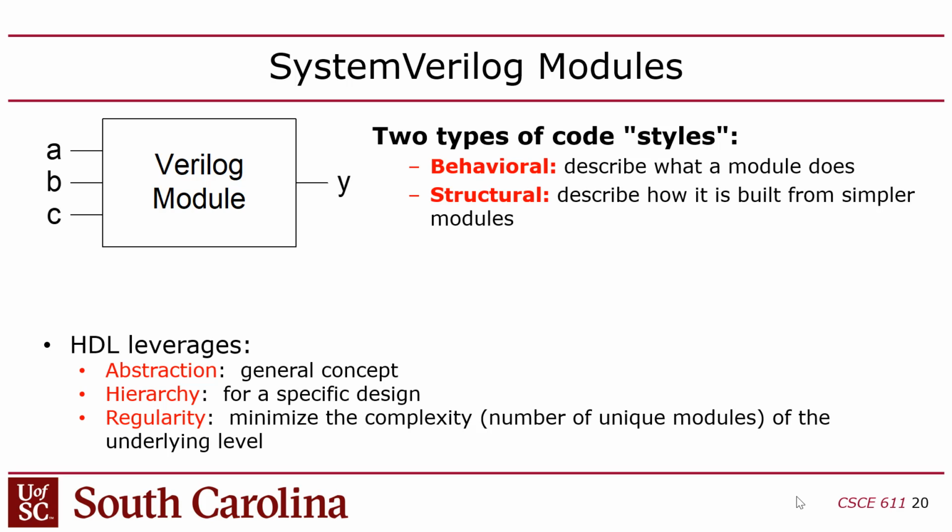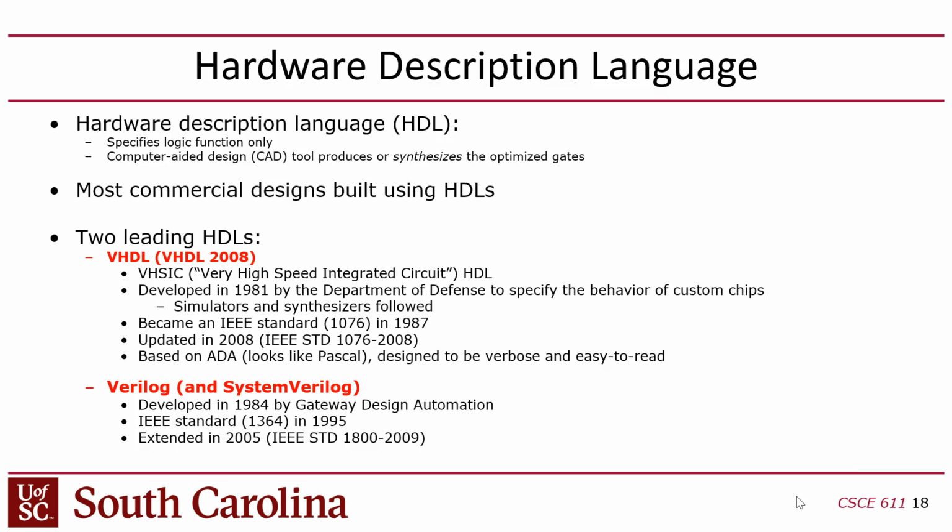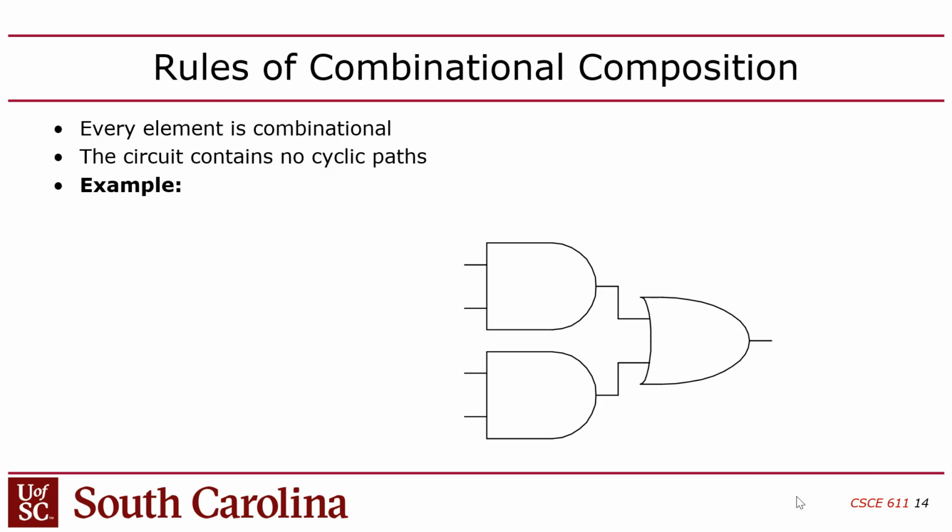Typically the first line of the module is going to be your inputs and outputs. You're going to define what the inputs and outputs are. And then inside the module, you have the behavioral description. Okay, and then the timing specification is usually something you get from the CAD tools when you deploy the module. All right, so let me back up here a minute.